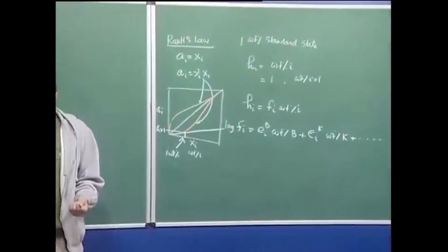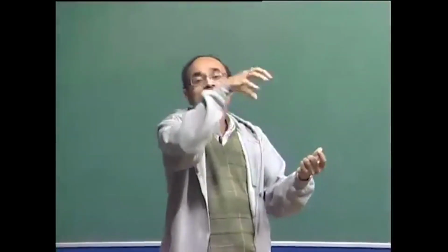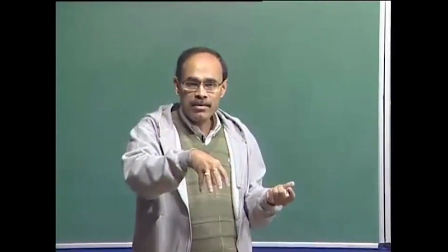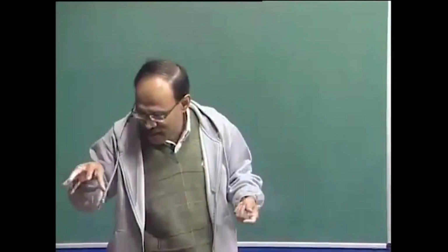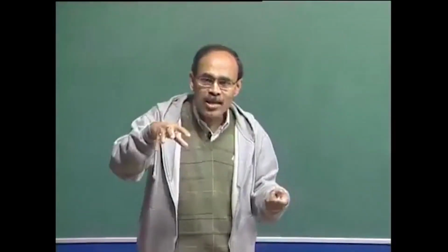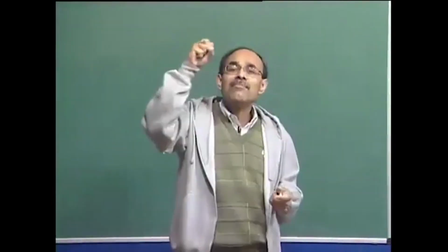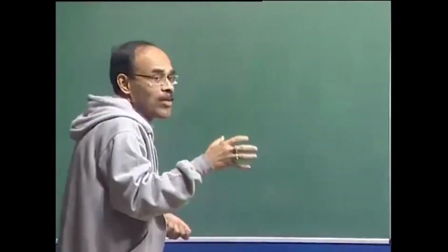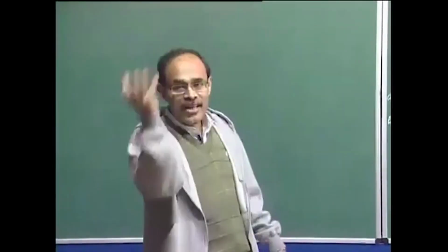Now, you must understand that when I have iron and sulfur, for example, I can measure the activity of sulfur. Now, when you introduce carbon into it, it becomes a three-body problem. So, there is carbon-sulfur interaction, carbon-iron interaction, and sulfur-iron interaction. As a result, in a two-component system, iron and sulfur, whatever activity I measure, in the presence of carbon the same activity will not be measured.